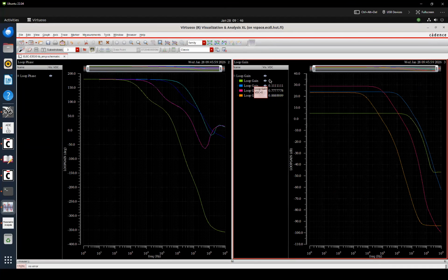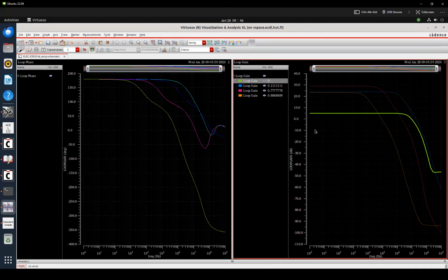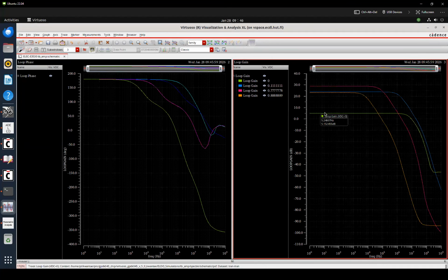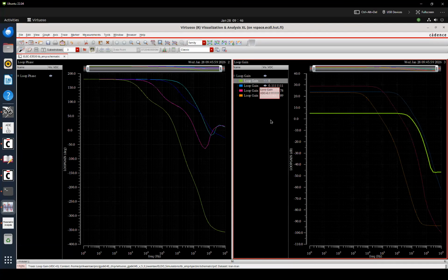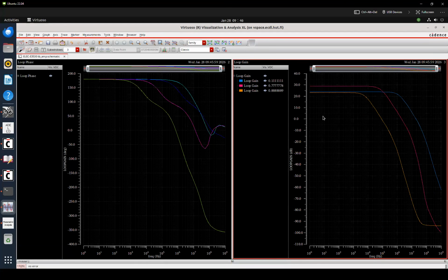Anyway, if you set VDC equal to 0 volt, then obviously the amplifier doesn't work at all, because 0 volt should be buffered to the output, and the output voltage is 0 volts, then the output NMOS doesn't work. Its VDS is 0 volt. So it doesn't make sense, so we need to drop this option, VDC equal to 0 volt.